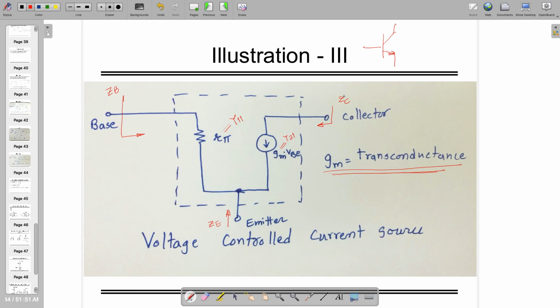Make sure all other terminals are zero. Apply the node voltage VTH, and the other input terminals go to zero, and find the current flowing into the network. That current divided by voltage gives the equivalent Thevenin impedance. So find out what is ZB.